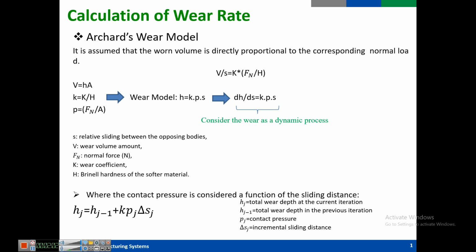As I said already, for my wear simulation I use the ARCHARD model. In the ARCHARD model we usually use load, normal load or pressure, and sliding distance, and another important one is the wear coefficient, that you can find by experimental tests such as the pin and disk test.